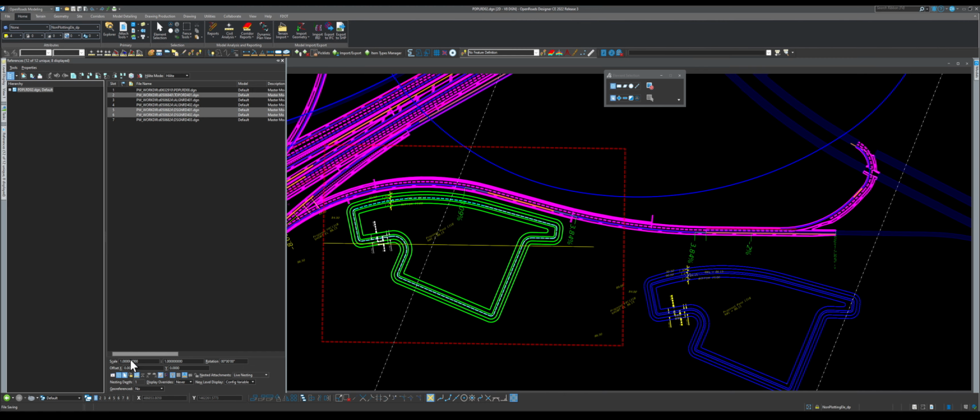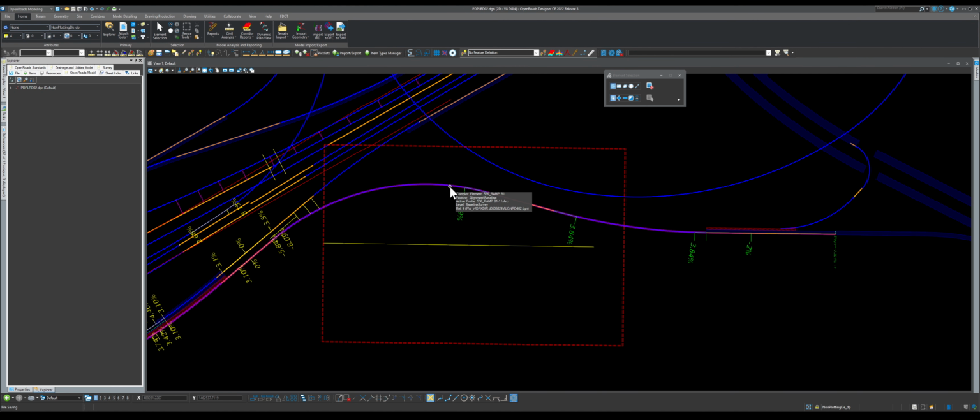By the way, don't worry about these. Whoever is in charge of these alignments, they love their construction lines, non-plotting. That's why they have these. These are for them. I mean, it doesn't matter. You can hold, right click, and then level them off. They're not going to appear in printing anyway, period. Even this one, you can take it off if you don't want, but I already have it active here. So let's go to another one so I can turn it off.